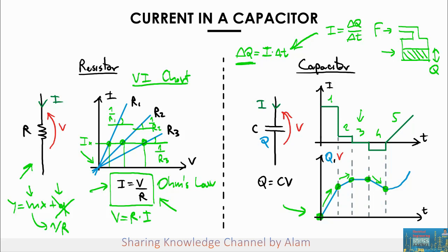So I believe that if we have to summarize in a few bullets what we learned at the beginning of the exercise, we really learned two things. One is that whether the charge increases or decreases really depends on the sign of the current. When the current is positive, the charge is increasing, and when the current is negative, the charge is decreasing. So in the fifth period, despite the fact that the behavior of the current is kind of strange, it is always positive, so we expect the charge to increase.